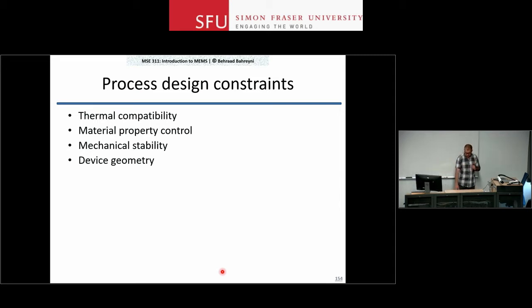So make sure that those are steps. Order of steps is very important, right? So if you go back in CMOS manufacturing, for example, as a familiar example, in the early days, you created the drain and source of the terminal first, then put down the dielectric for the gate, and then put gate material, usually a layer of, let's say, aluminum on top of that. Well, as the processes got more and more complex, as we started to reduce the distance between drain and source, that process turned out to be less suitable for scaling.